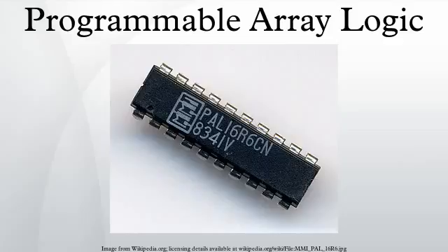National Semiconductor was a second source of GAL parts. AMD introduced a similar family called PALCE. In general, one GAL part is able to function as any of the similar family PAL devices. For example, the 16V8 GAL is able to replace the 16L8, 16H8, 16H6, 16H4, 16H2 and 16R8 PALs.